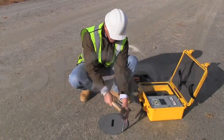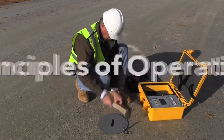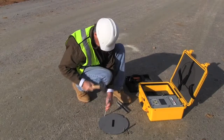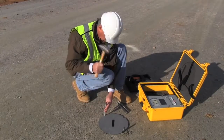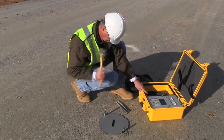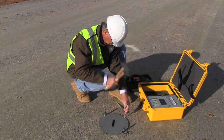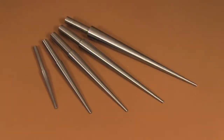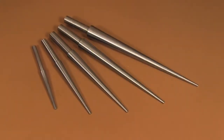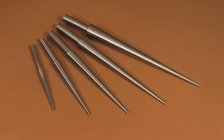The electrical density gauge measures the dielectric properties and moisture levels of compacted soil using high radio frequency, traveling between darts driven into the soil being tested. The dart's depth of penetration positively determines the depth of measurement. Darts are available in 4, 6, 8, 10, and 12-inch lengths to correspond to different lift heights.